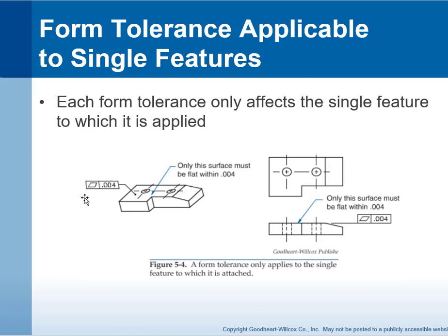And we could show it like this, or we could show it on an extension line here, and then we have the flatness within 4. Okay, so this means the same thing. We're talking about the flatness only applies to this upper surface of the part.